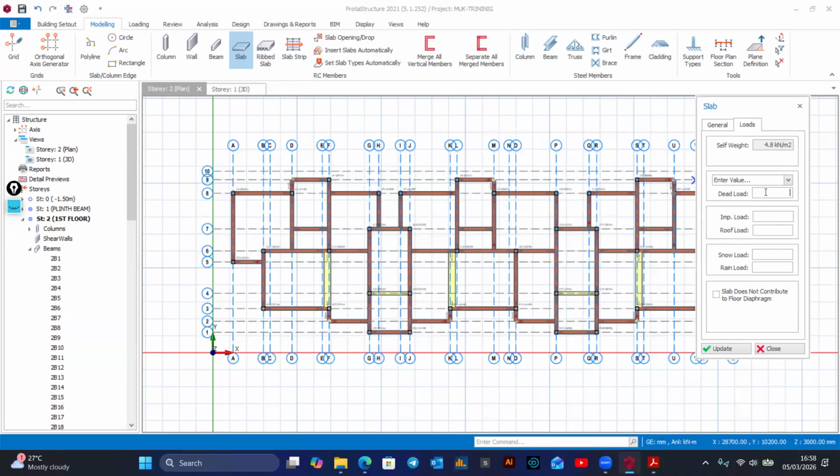So the dead loads we are going to consider here are particularly self-weight and the floor finishes. You can look at tiles, you can look at screed. But once you have gone through some calculations, you find that most of the finishes will not exceed 1.5 kilonewtons per square meter, because here you're dealing with area.